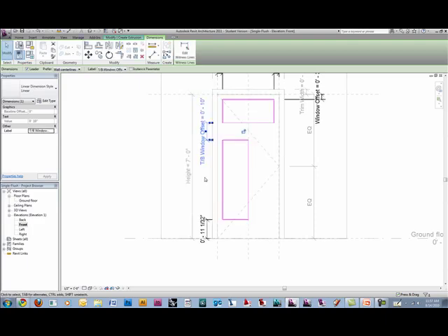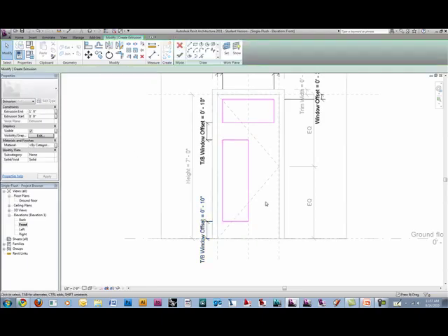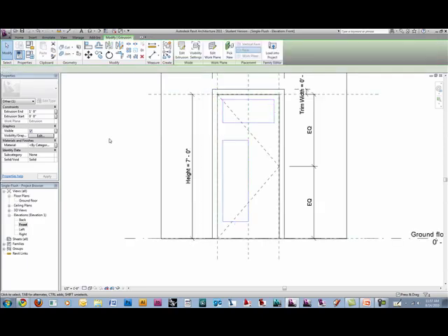So that's a constraint again. There it is. Those are good to go. And now I want this one to be the top to bottom window offset. It'll automatically flex that one. So I think that's about all the modeling we need to do for those 2 little windows, and that's good.